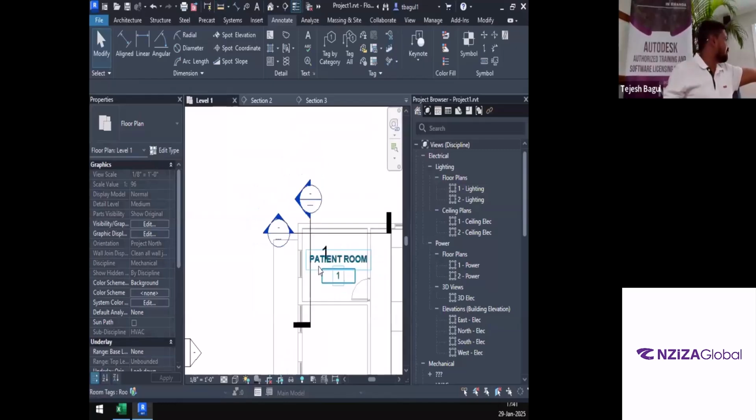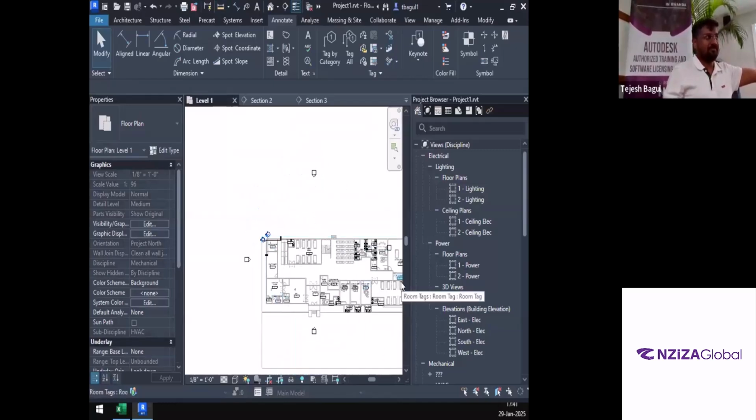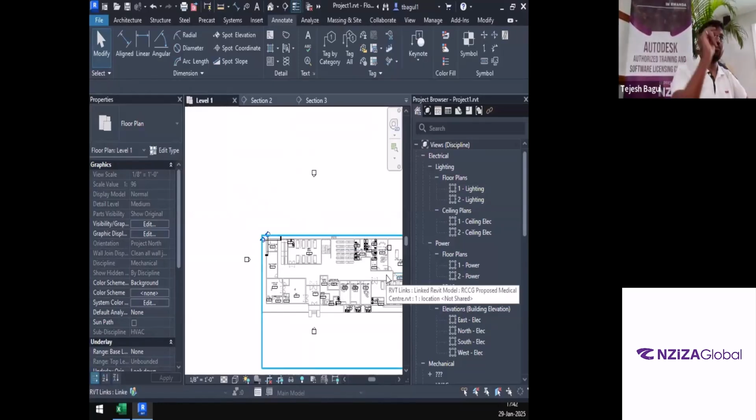Now, if I was doing this project, I would go one by one and do everything. Okay. I know that is a lot right now. I do understand we are running against the time. But the thing is, I want you to try this out. This was just a trial. You now understand, the biggest thing is you now understand where to find the minimum outdoor air changes per hour, where to enter it in that spreadsheet, how to find the area of the walls, windows, how to find the U value, how to find the outdoor air conditions, the ASHRAE Meteo, how to find the set point, indoor air conditions, ASHRAE 170.